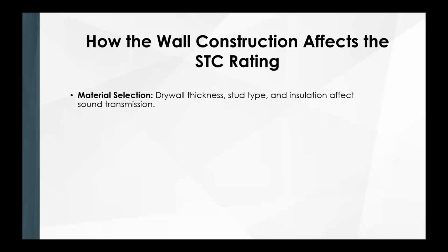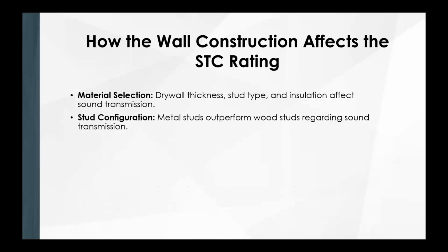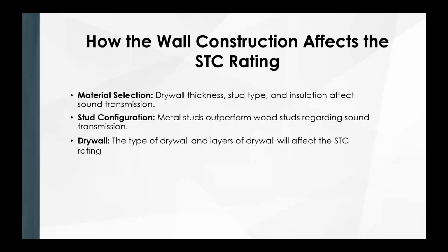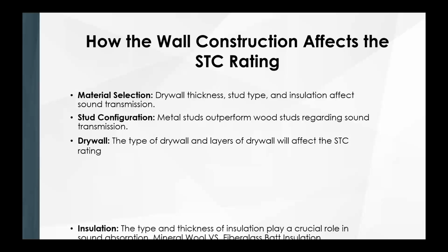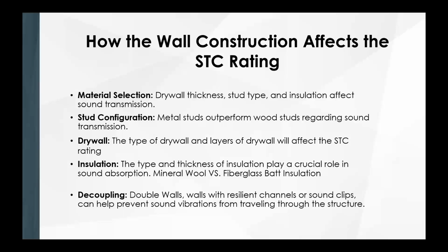Material selection, drywall thickness, stud type, stud thickness, insulation, all that's going to play a role. Stud configuration. We all know as a general rule that metal studs outperform wood studs, but also the difference in metal studs and the gauge of the thickness of that stud will also affect the STC rating. Drywall, types of drywall, layers, that will affect it. Insulation, R11, mineral wool, R13, all that is going to play a factor.